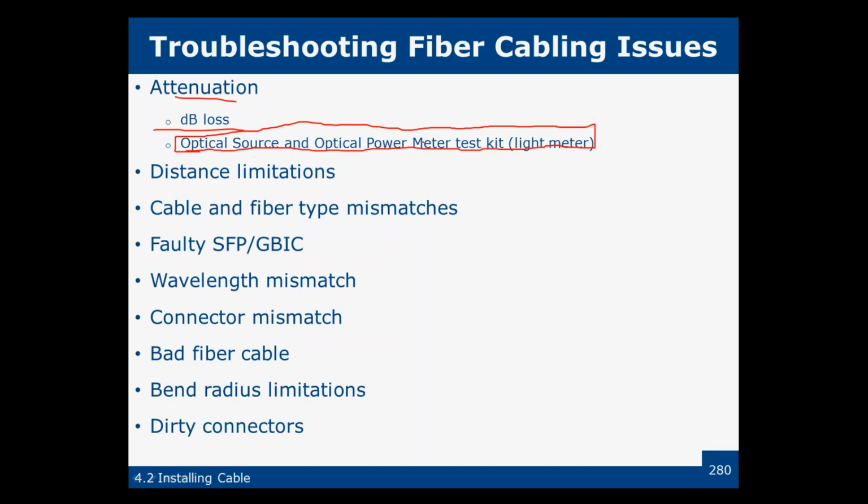Also, we don't have crosstalk, we don't have RFI, we don't have EMI with the light signal, so you can have a much lower signal when you repeat it. Remember, since it's binary, 1 or 0, off or on, as long as the signal's greater than the noise, you don't have a whole lot of decision making. It's either a yes or a no.